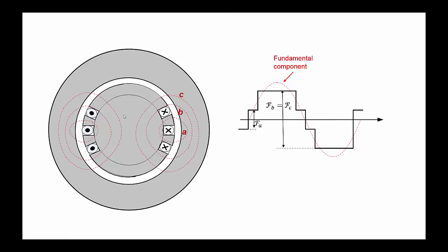So later on, when we discuss AC machines, I start by using the number of ampere turns or coils and currents in slots, and I adjust them to give me a waveform that is sinusoidal. You know that I'm trying to get an MMF that is sinusoidal, because as we'll see later on, if the flux density distribution is near sinusoidal, then the voltages induced will be sinusoidal. We'll discuss this in the next, not the following, but the next presentations. We'll talk to you then.